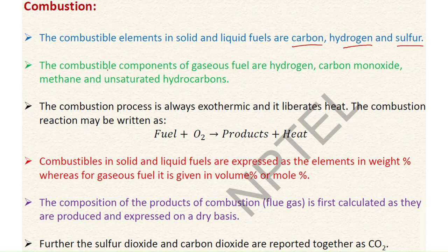Okay, the combustible components of gaseous fuels. These are for the solid and liquid fuels, and for gaseous fuels, there are some more added to these: hydrogen, then carbon monoxide, then methane gas, CH4, then some unsaturated hydrocarbons, mainly olefins, and if some triple bond hydrocarbons are present, then they are also combustible components of gaseous fuels.